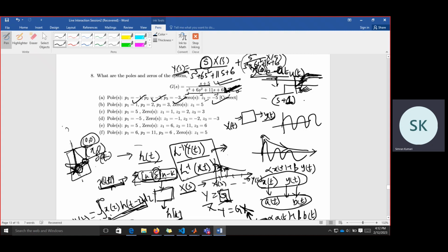Also, when the zeros are in the right half plane, we define the systems as minimum phase or non-minimum phase, basically the lag of the system. If the poles are in the left half plane, these are causal systems. So when we give input, output will be observed after some time. That is the phase shift with frequency that we say. This will increase if the zeros are in the right half plane. As of this, I can recall, but I think I can give more insight on zeros in the next session. Is this clear?